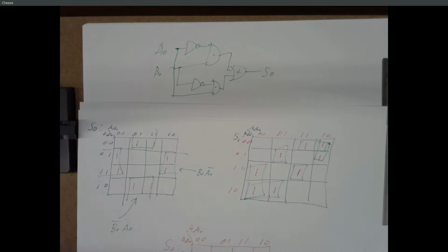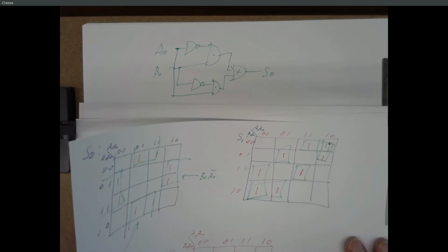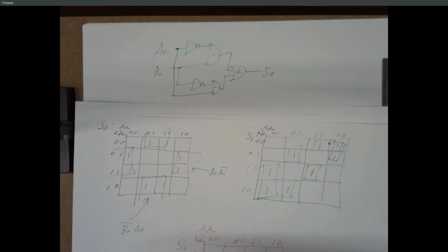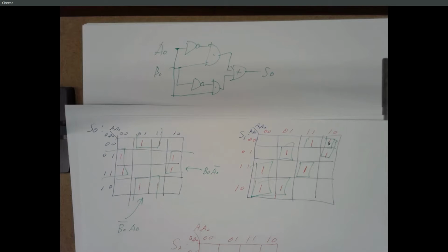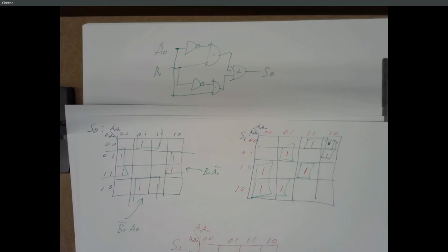And it's all kind of, you hear the term random logic. It's not really random, but there's no easy pattern to see in this. So you got 19 gates, you got wires hooked up to all of them, and you test your circuit and it doesn't work, and it's kind of a pain. And that's just for S1. Then you got to do something for S0, and you got to do something for S2. And this is to make a 2-bit adder. It can go up to 3 plus 3. What if you wanted a 32-bit adder?